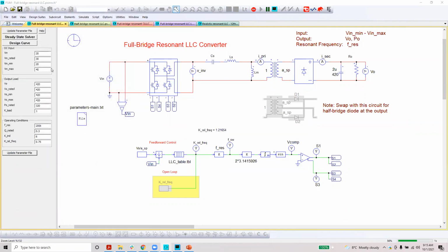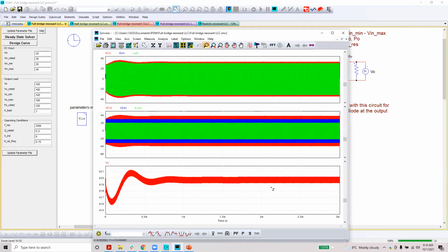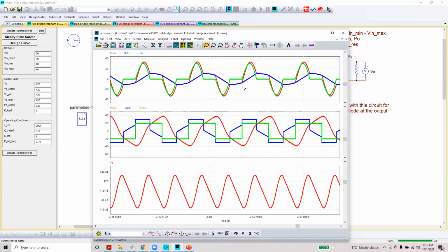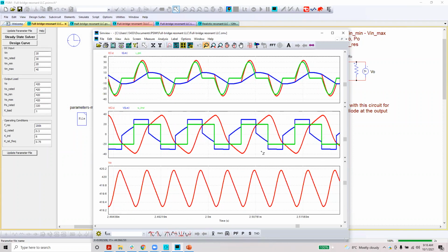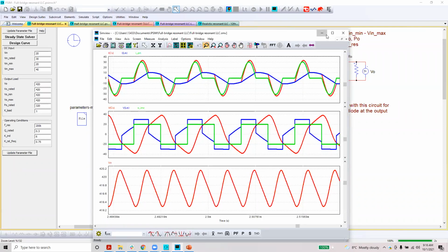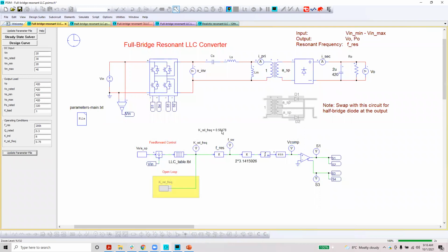And you can see at the lowest voltage how much frequency you need here. So for that, of course, you need a gain of around 1.5. And you find out, again, it's regulated at around 420. And you can see how much DCM you have gone into here. So we have gone too much below resonant. That is around 0.56. So that's your K, the relative frequency here, right?